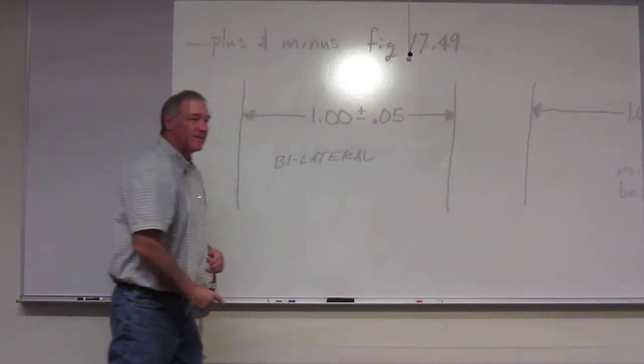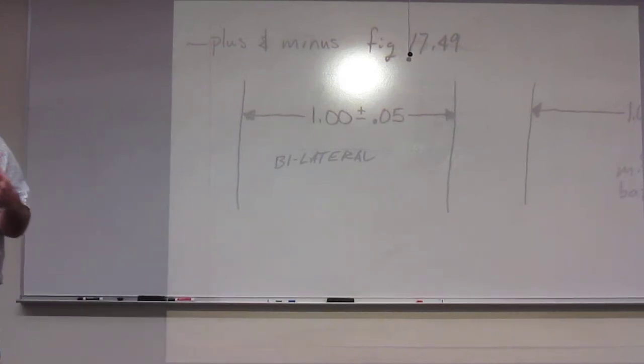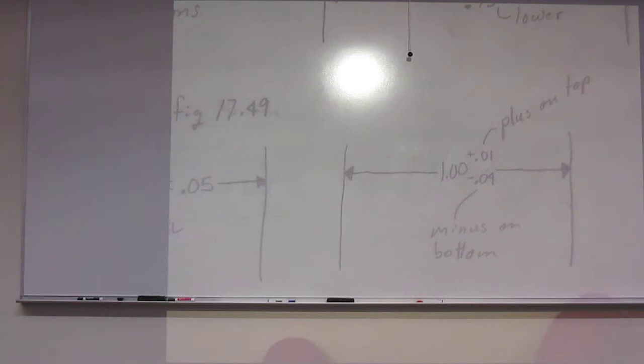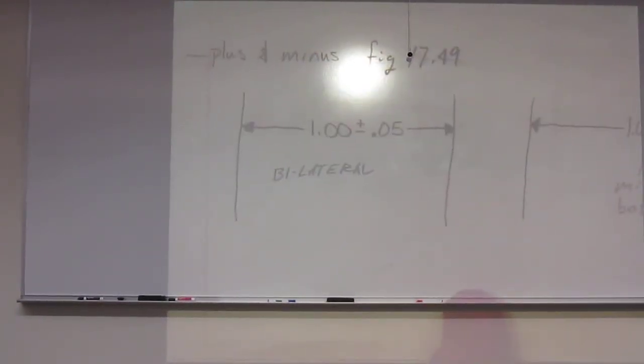You're going to find when you do this, this is really where you get into the fine details on how you're going to construct something, okay, and how it is going to perform through the life of the part. You really think about that. In essence, you're getting into the manufacturing process here. All right, any questions about direct tolerancing? Direct means you're using limit dimensioning, such as this one, or you're using bilateral, like these two.